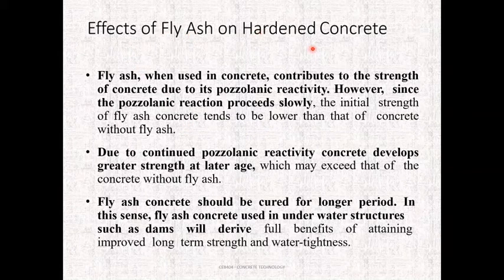The effect of fly ash on the hardened properties of concrete. The fly ash contributes to the strength of the concrete due to its pozzolanic reaction. However, the pozzolanic reaction proceeds slowly, hence the initial strength of the concrete is lower when compared to the control mix without fly ash. Due to the continued pozzolanic activity, the concrete develops a greater strength at a later stage, which exceeds the control concrete. The fly ash concrete should be cured for long enough.